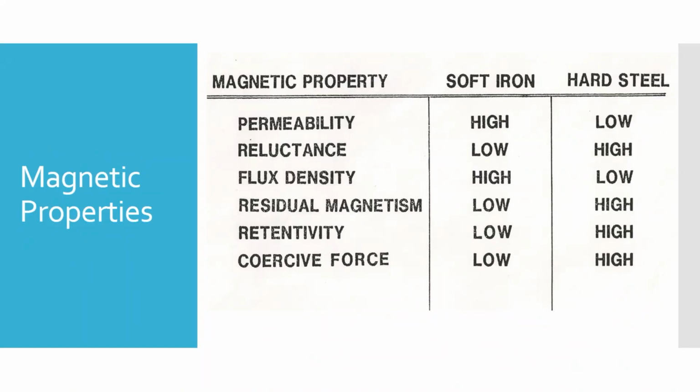It doesn't want to demagnetize. So it's basically materials where it's easy to get the poles to align. It's also easy for them to scramble back up again. Whereas things where it's hard to get the poles to align and get that magnetic field, it takes a lot more work to undo that as well. And so sometimes you may need a couple demagnetizing passes to make that work.